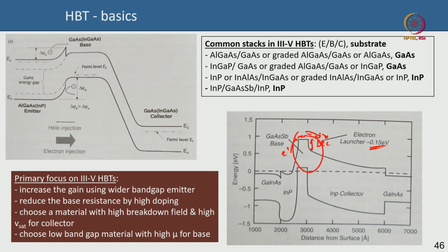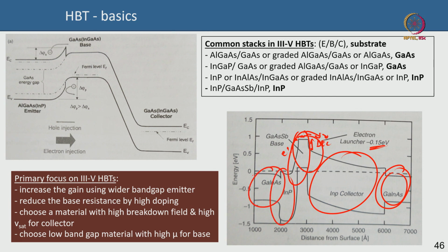Okay. So this is a very unique heterostructure that you can design, and this is a subcollector. Again, you can use a material with very high mobility and very high doping that gives you very low contact resistance in the collector. This material gives you pretty good mobility and velocity, but this indium phosphide is a wider band gap that gives you larger breakdown voltage, but you do not sacrifice that in the emitter because you have a highly doped InGaAs emitter here. This kind of mix and match play is only possible in compound semiconductor.